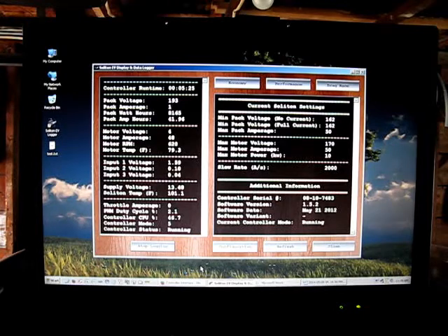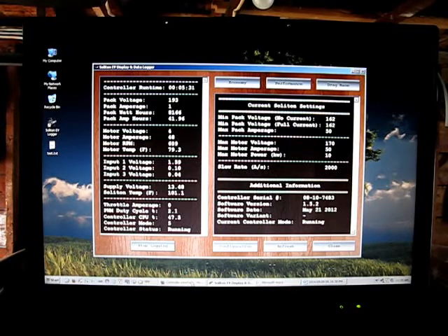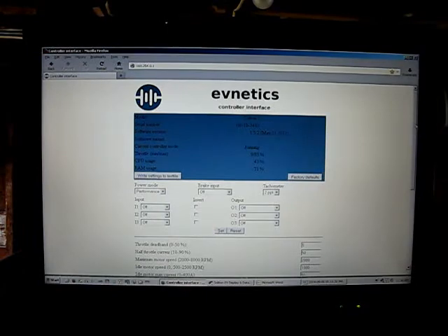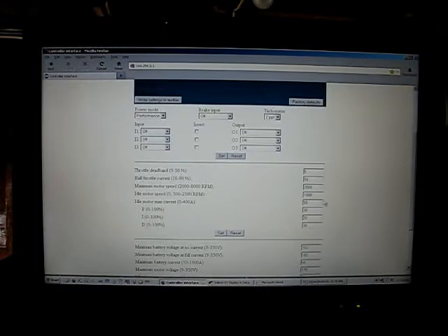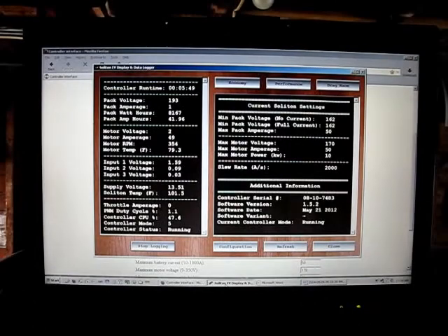It's kind of strange. But what I found, just doing some experimentation here, was that if I go into the settings, the Soliton settings, and I adjust the idle motor max current, we're going to go ahead and set that to 100. And again, just before I hit the button, let's go ahead and check. Again, it's dropping down, 250, 230. And so I think this is what happened last night, is that it had gotten down to 100 RPMs, at which point it just shut off.